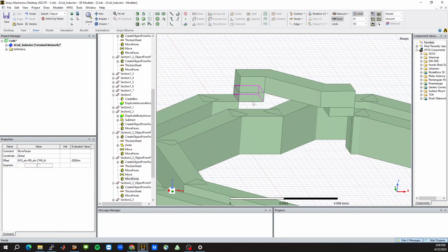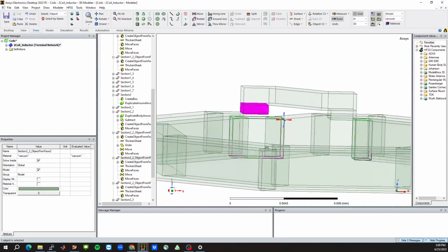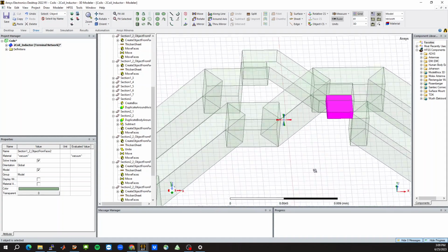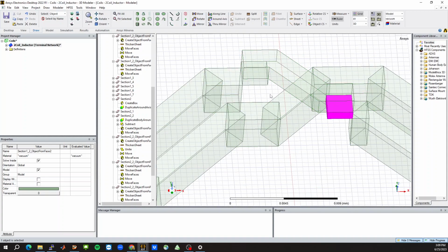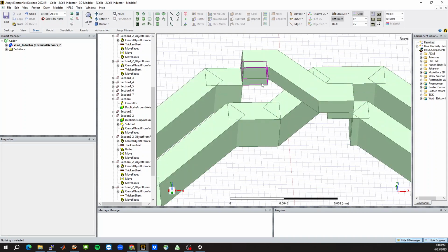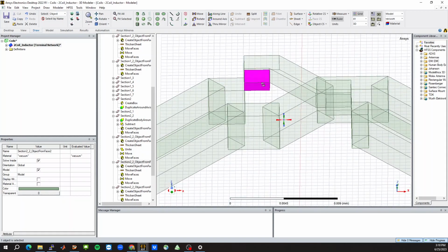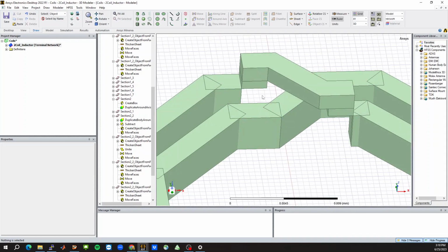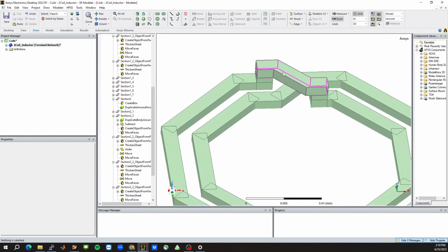Okay. So now you see that this box acts like a via. Of course, we can't make individual vias because that would take forever to simulate. I'm just making a via cube. And you can find what the effective conductivity of this should be by simulating a set of vias and then finding what the equivalent conductivity is. Anyway, so let's view everything.